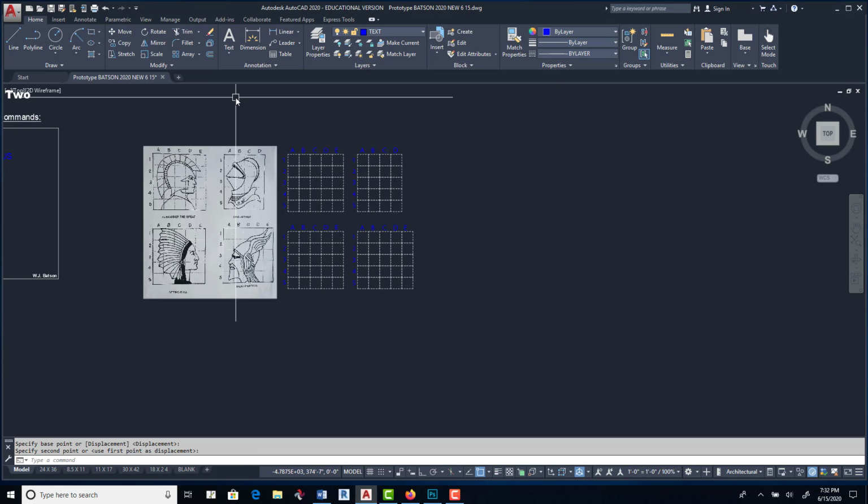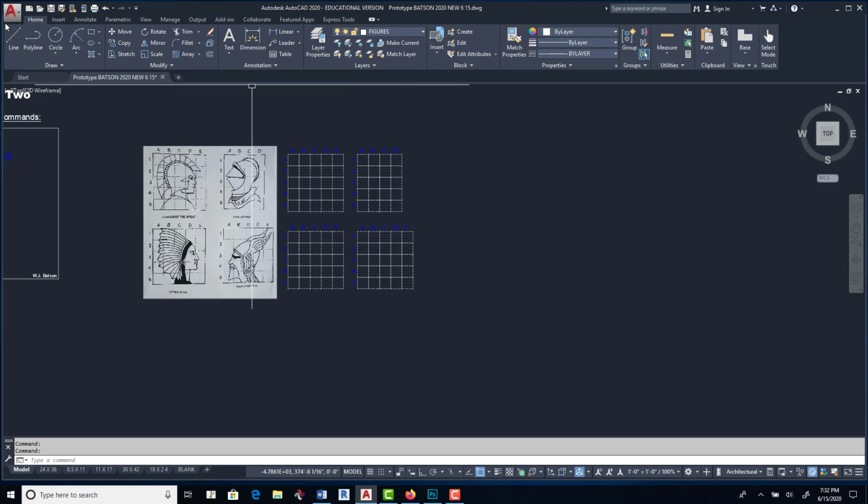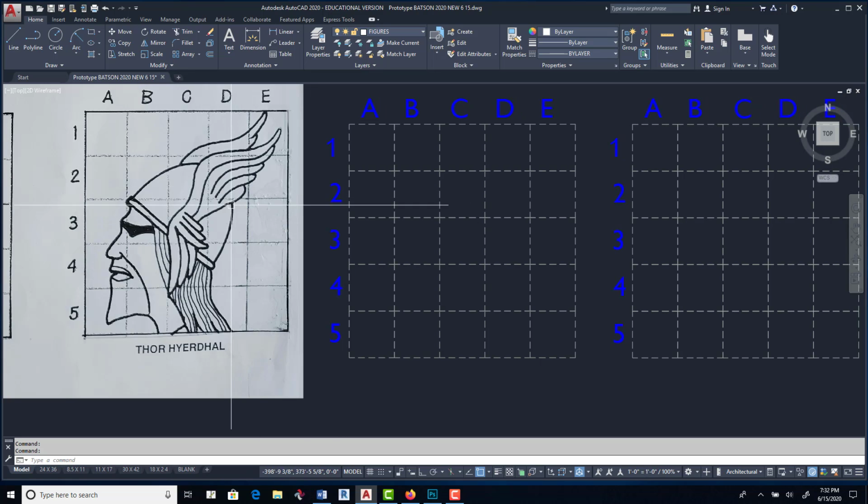There you go. So now let's go to the figures layer. Let's go to layer, and we have one called figures, right? So figures, double click, make sure the red arrow is there, X out of there, roll your mouse wheel. Now what we're going to do is go to Polyline, select the Polyline, and sometimes you want to take your snap off because it'll snap to these little intersections and you don't want that.